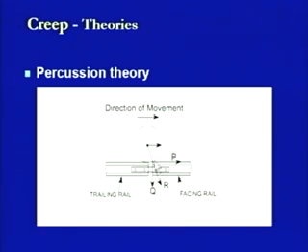So, at the point of this contact of the wheel and the rail section in the forward direction, there will be an impact force which will be acting in this inclined direction like this. Now, if we take the two components of this one, because this rail section is moving in this direction, we will be having a component P which will be in the longitudinal direction, that is the movement of the wheel, and we have another component Q which will be working in the downward direction like this one.